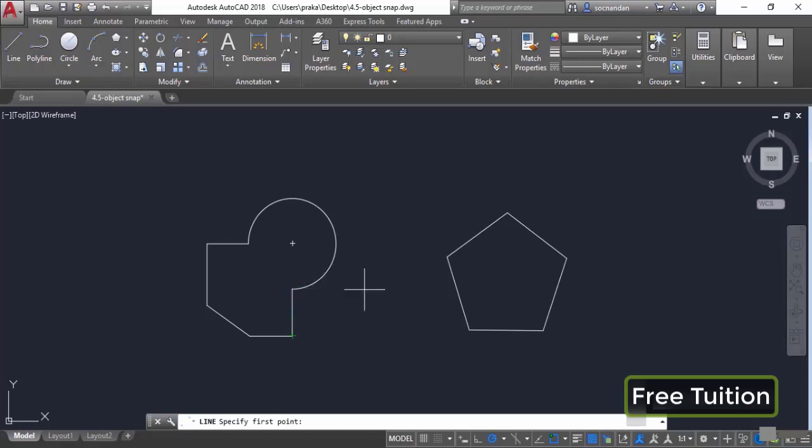So if you want to take reference of this, simply click on Object Snap Tracking, move back to this point, and now move in this direction, and you'll have this tracking vector. That will take reference of the existing object snap. So you need to ensure that Object Snap Tracking is on if you want to take its reference. Now here also I'll press Enter again. I'll go to this midpoint or the center, but I'll not click, and here we have the reference.